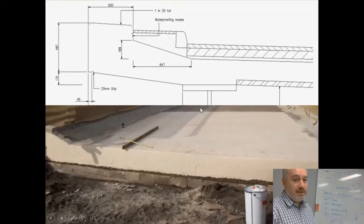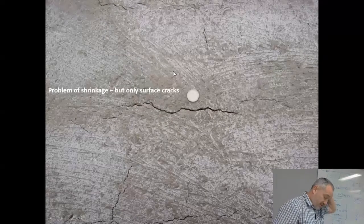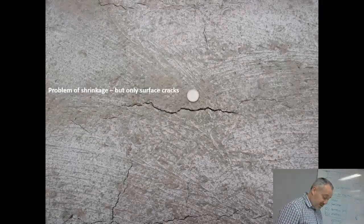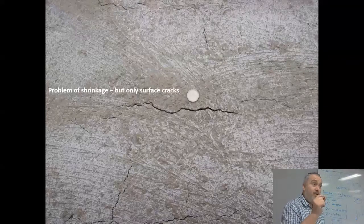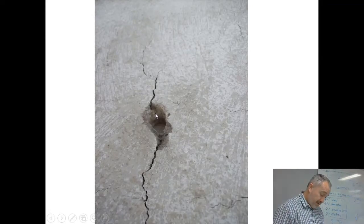So we've got our concrete slab. This is just showing the bitumen and also the pathway. There were some cracks in the concrete, which we're slightly worried about. Concrete does crack. You're allowed like 0.3 mil cracks. But when they drilled down, they found that the crack was just on the surface, so it wasn't all the way through the slab itself.